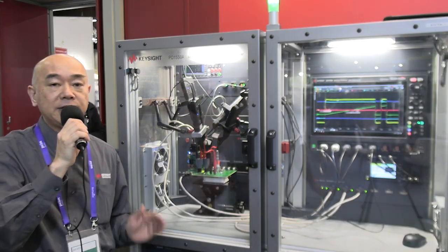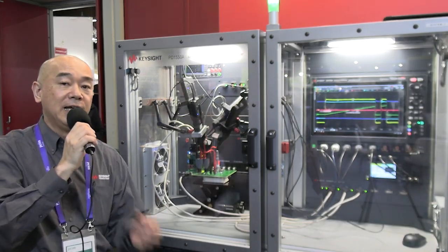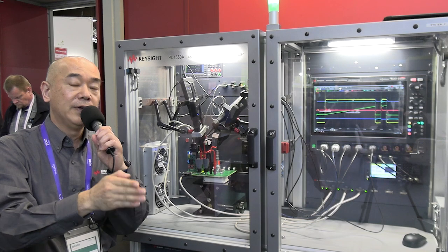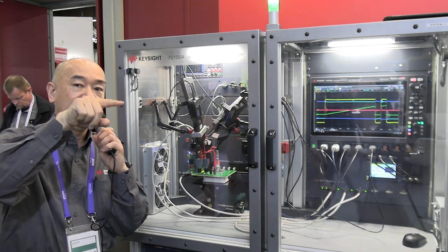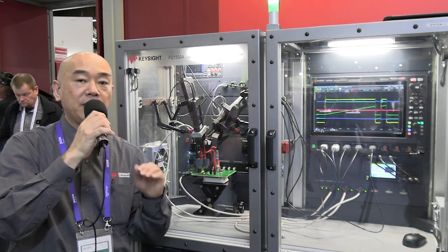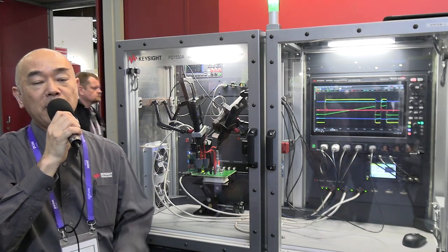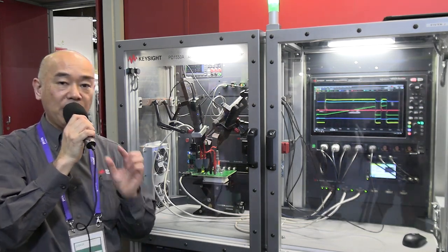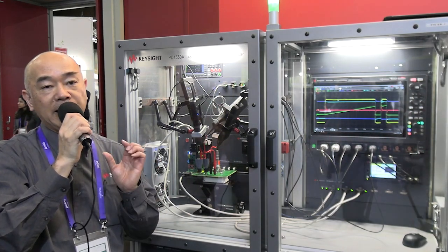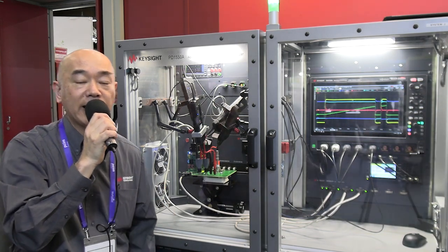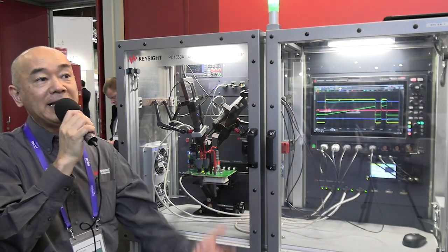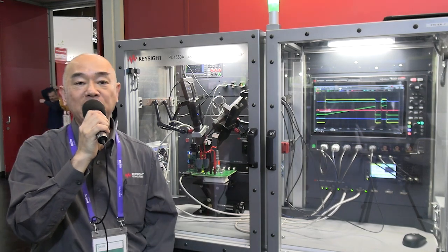Double pulse test is to give 2 pulses to the devices, which turns on the device, and then turns off the device at the edge of the first pulse, and then turns it on again with the single double pulse. You have off characteristics and the on characteristics of the power device or power module. So it's a very easy method to characterize switching characteristics, and also it's a kind of standard method, but it's not very easy to do because of the high speed of the power devices.